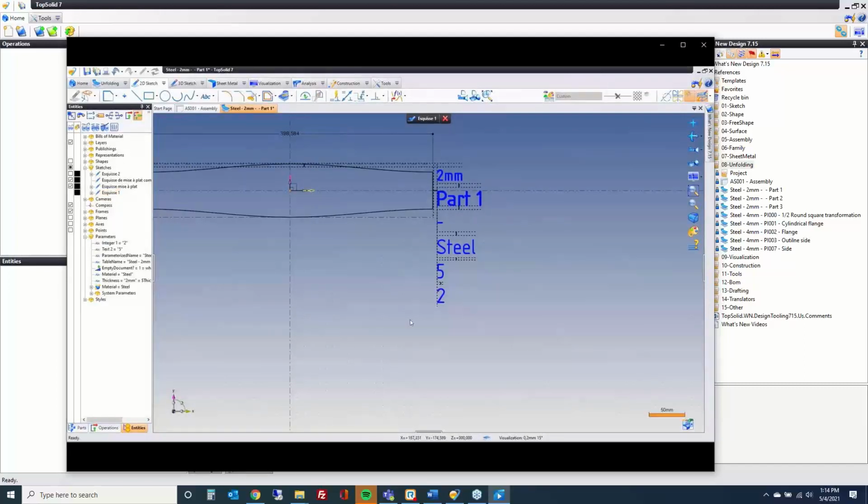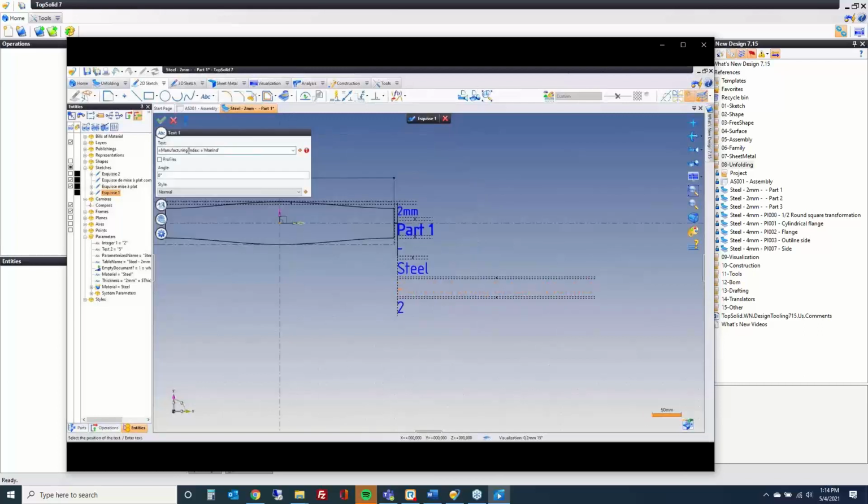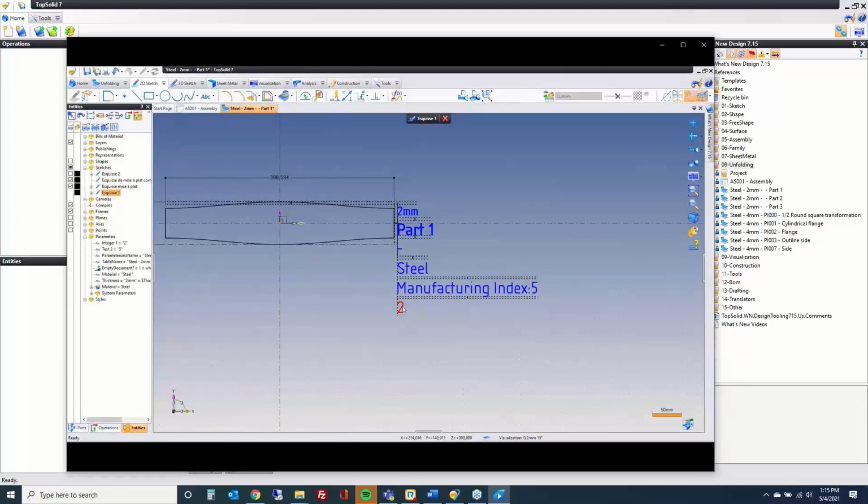But what I'm showing you first is the fact that, okay, we're passing the bill of material information, but it would be better if we could help it out, give a little description. So now we're going to add some random text in here. So we're just going to do an open quote, manufacturing index, colon, close quote. Okay. And then we're going to put an ampersand sign in. And this allows us to take text, that's what's in the quotations, plus an ID or a parameter, and create the specified text string that we're after.